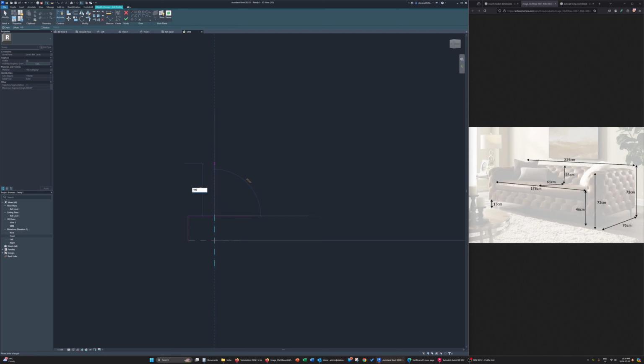In order for us to get this measurement, we're using 46 centimeters minus 13 centimeters. So it's going to be the difference between both. And once again, we just have to go inside just enough so that we can capture that full intent. In this case, I'm going to use 100 millimeters, and I'm going to create a nice little box like this. So now I can almost delete this part. And essentially what I'm going to do is I'm going to round my edges as much as possible. In this case, I'm going to do 50 millimeter here.